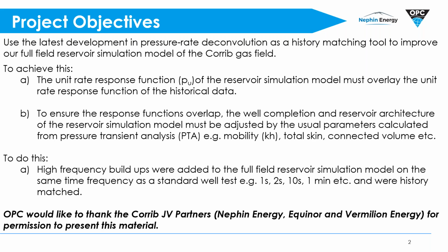And B, to ensure the response functions overlap, the well completion and reservoir architecture of the reservoir simulation model must be adjusted by the usual parameters calculated from PTA, e.g. KH, total skin, connected volume, etc.